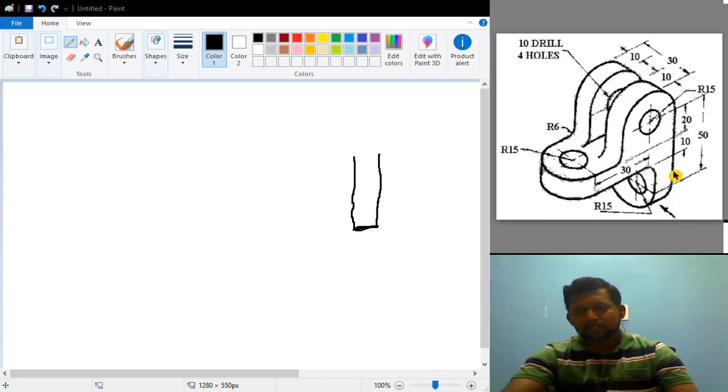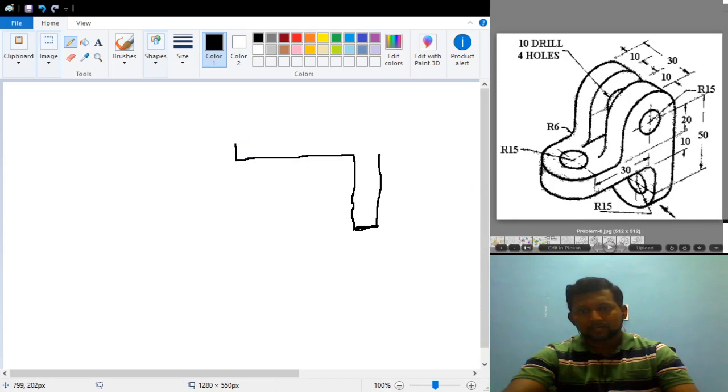Okay, so just now I have completed only 10 mm of this one. So that means from here directly I can draw a length of 50 mm. Okay, and from here another 10 mm for this semicircular block. I am talking about this semicircular block over here, and from here I am drawing 15 mm inside. So this 15 mm is for this particular center, okay.